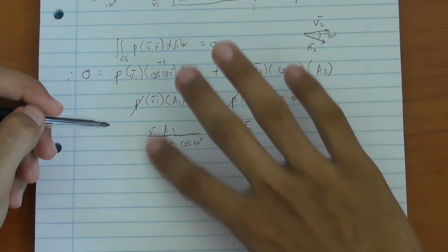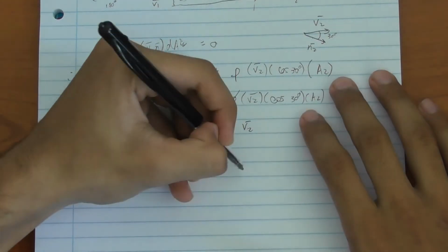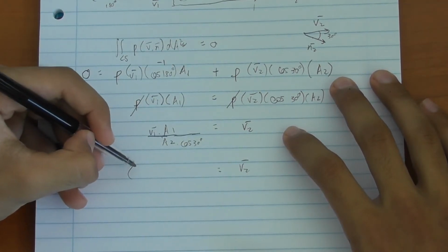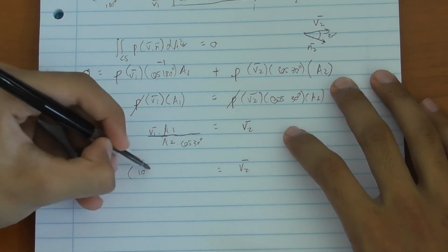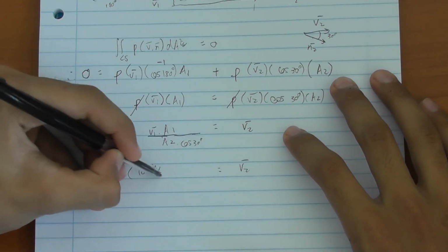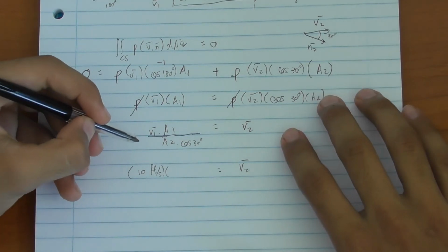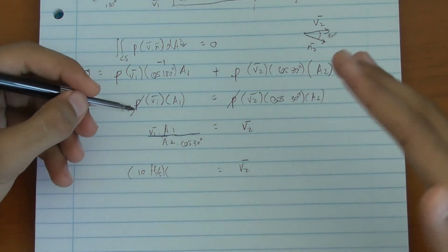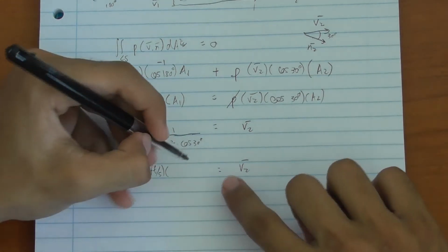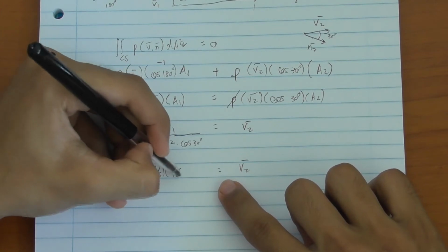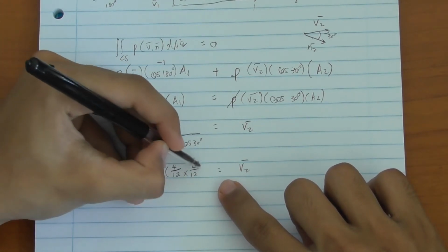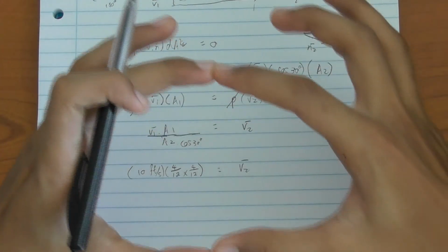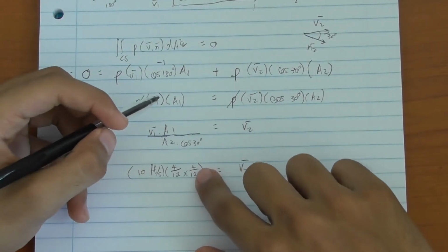Let's start substituting in numbers. So V2 is equal to V1, 10 foot per second, multiplied by area 1. Now remember, area 1 is in inches. So to convert inches to feet, you need 12 inches to make 1 foot. So you have 4 inches divided by 12 multiplied by 4 inches divided by 12. That's because you have 4 inches multiplied by 4 inches to give you the opening area, 4 by 4, and I've divided by 12.